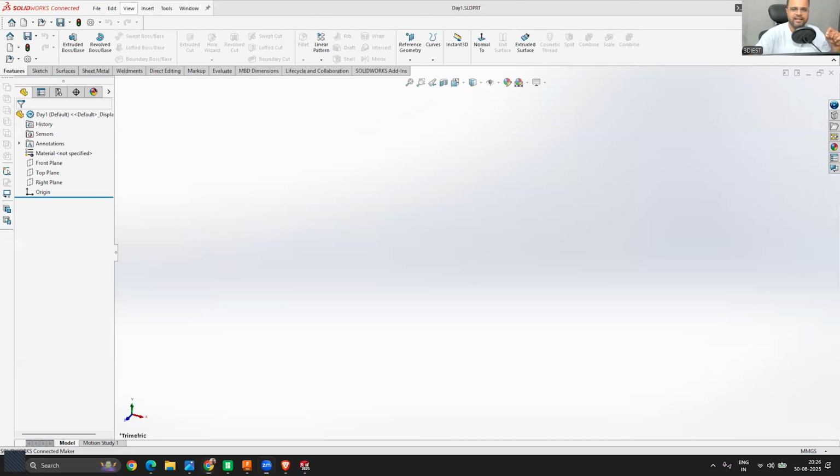The first option in the menu bar is the File menu. If you click on the File menu, you can see options to start a new file, open an existing file, open a recent file, open drawings, and close this one as well. We also have multiple options like save as template, pack and go, and share. We have lots of options available here that we'll explore while doing designs, like how we can use these options. But from here, you can access all these options. So I was talking about inside SolidWorks, the top level that you can see is the menu bar.